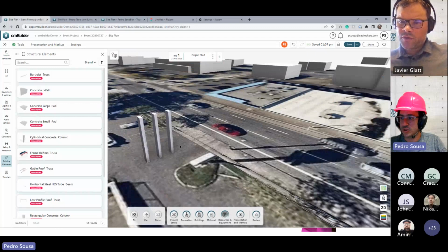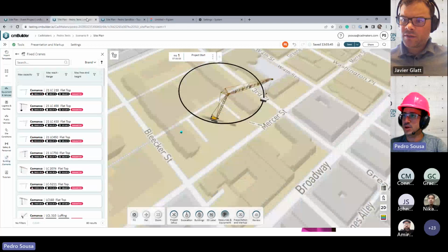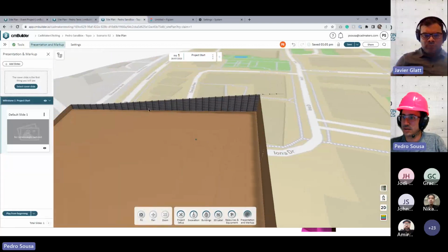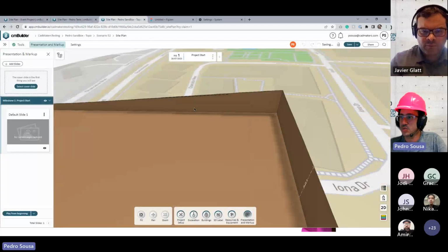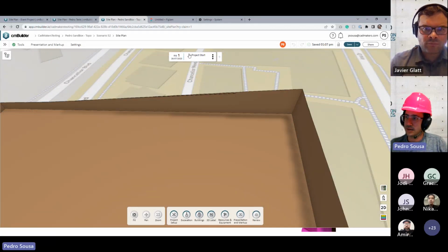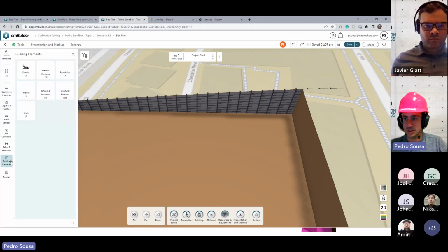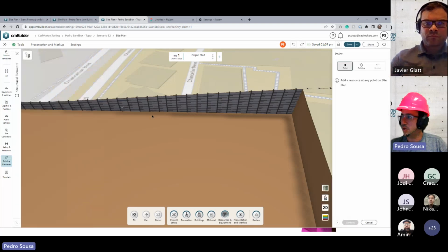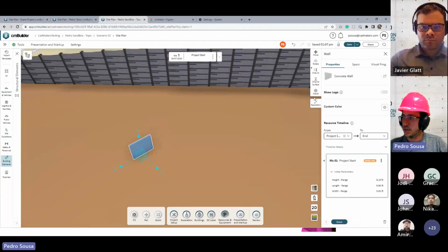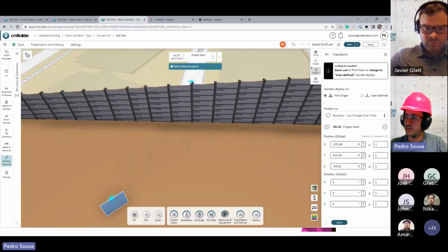Which walls are you talking about? Without having to use the rotation feature. So if you're talking about walls, something like this, without using the rotation feature, we will need to create a line that is anchored on a slope, like I did for this guy over here, or you can create a point-based resource, let's say concrete wall, and you do a snap of one of the faces with the ground.